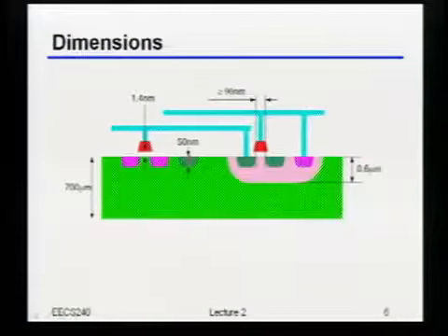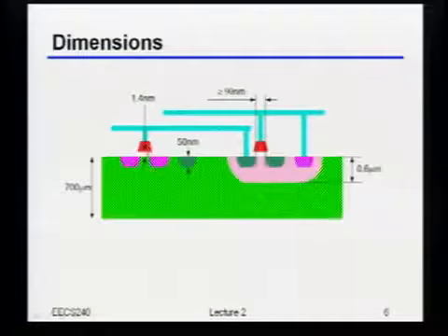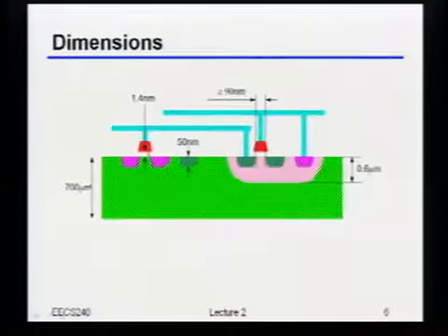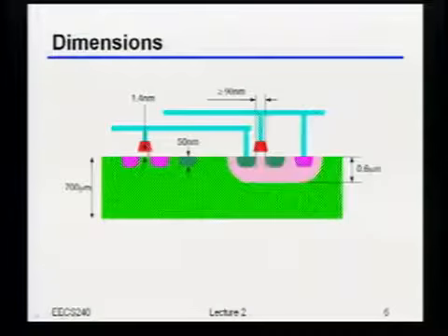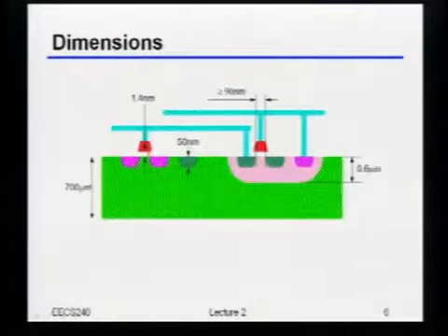Why might it be important that it's 50 nanometers versus, let's say, 10 microns or 500 microns or whatever? Any thoughts? Series resistance. Yeah, series resistance, right? Anytime you've got stuff that's thin, if you go for any appreciable distance, there's going to be resistance there. So just like you just said, every time you draw one of these transistors, actually there's some fairly substantial series resistance in those source drain regions. In fact, if you look at scaling, that's one of the big things that people worry about how they're going to take care of.